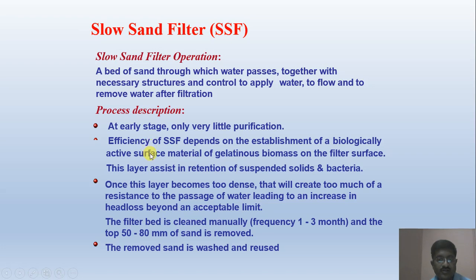Because of the continuous use, this layer is going to form, and it is very effective in removing the solids. Once this layer becomes too dense, it will create too much resistance to the passage of water, leading to an increase in head loss beyond the acceptable limit. So we have to keep watch on this. This head loss should be within the acceptable limit.